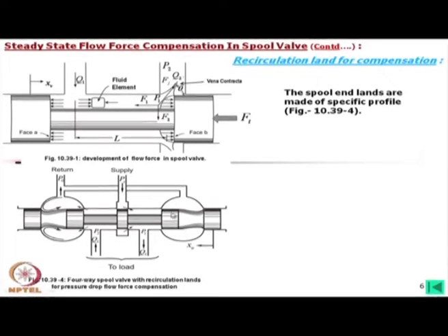Also the sleeve groove is made like this, but still the orifice is full rectangular, because the orifice area is calculated as stroke length times pi times this diameter. So this is rectangular, but instead of a rectangular groove, this is somewhat of a spherical groove inside.